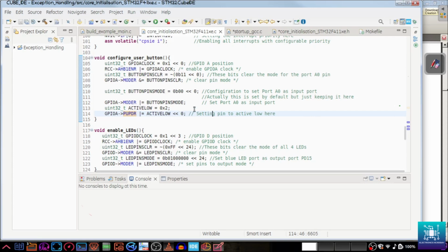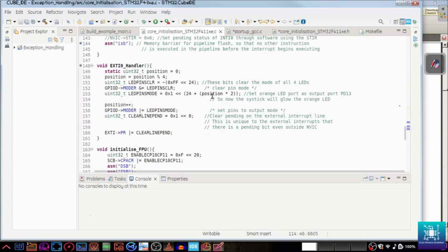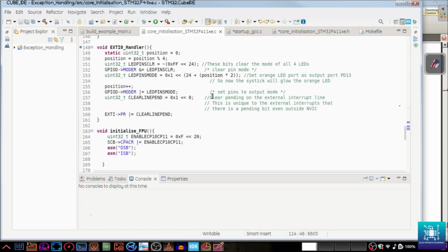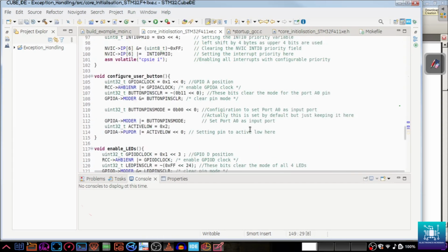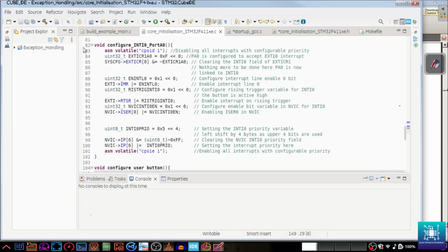This is the first point, from where you will press the button and your interrupt will come in physically. Okay. Then you have the actual setting up of the EXTI0 handler. Now the EXTI0 handler is going to be set this way. We need to go to the EXTI0. So here again we needed to make another change.